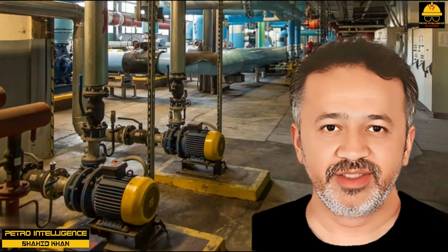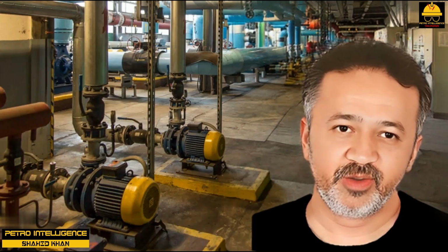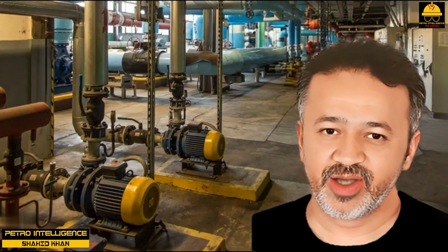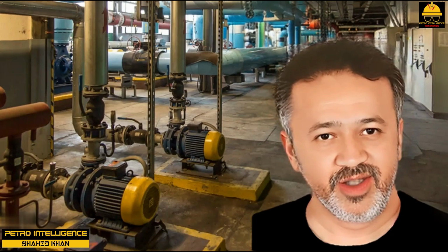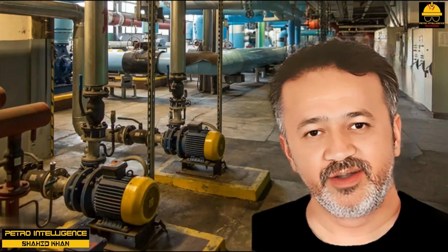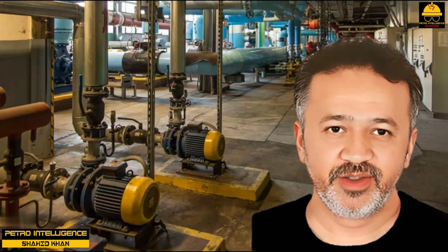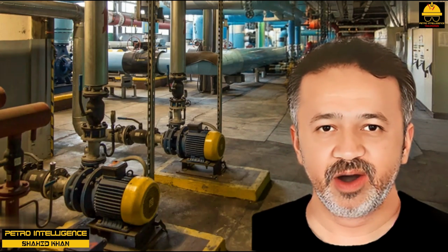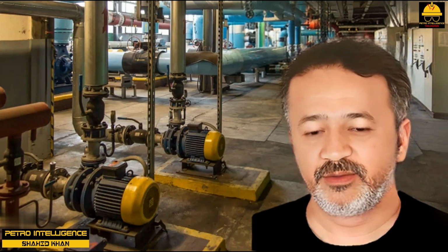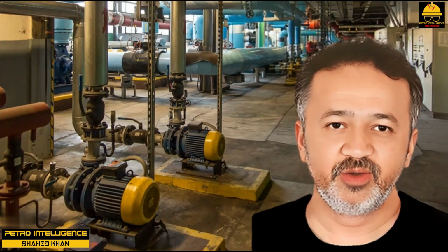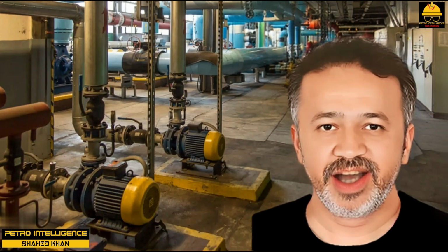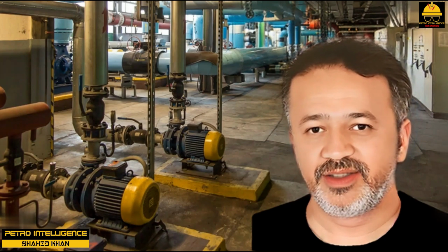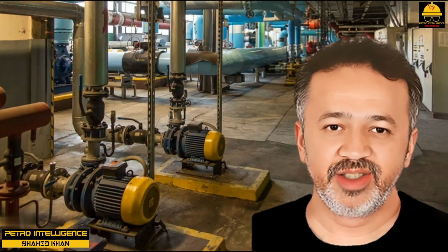If the load on the motor increases too much because the specific gravity of the fluid pumped has increased, the motor may indeed momentarily slow down. But due to the lower efficiency at the slower speed, the amperage load will increase rapidly as the alternating current motor slows. The FLA point on the circuit breaker in the breaker or switchgear house for that motor will be exceeded and the motor will trip off. To summarize, at home, motors can run slower for a minute or two before they trip off on high winding temperature. At work, motors trip off at the breaker after a few seconds of running slow, due to the high amperage load exceeding the breaker full limit amperage setting.